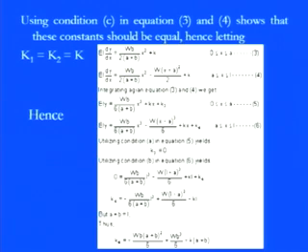The deflection at the reaction point is 0, as I told you, since there is a point load, so there is no deflection at the supporting reaction. So at x equal to 0 there is no deflection. If you put x equal to 0, the x terms and the y term will be gone, so k3 is 0.